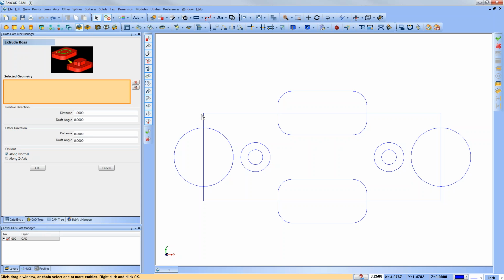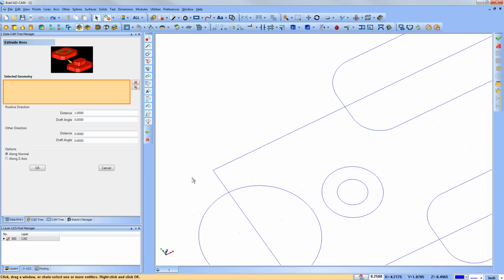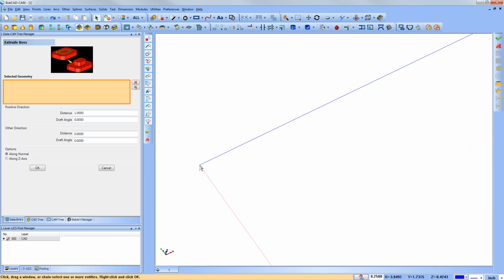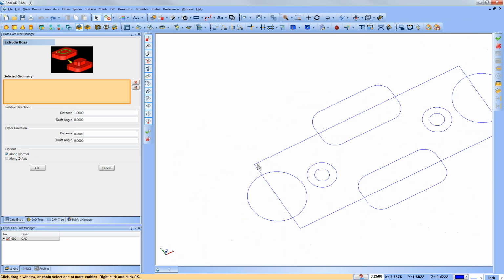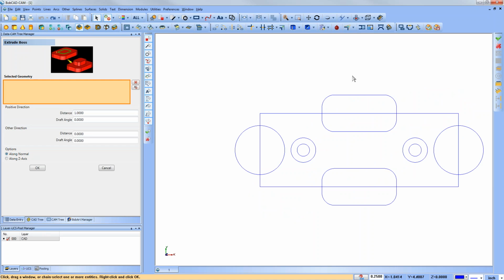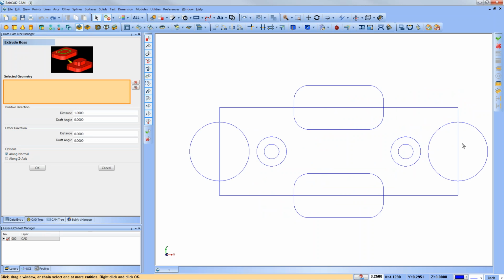That's another way to kind of talk about it. So the idea is that with geometry, maybe you have non-intersecting edges here, right? So trim or 2D tools would be used at that point. Trim two entities, or delete a line, or maybe redraw a line if the geometry is poor. So just ensure that you have closed chains, though.